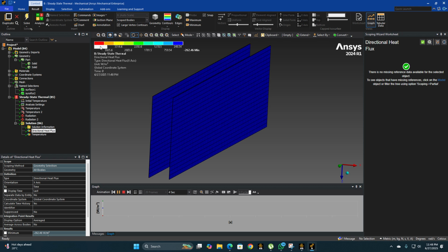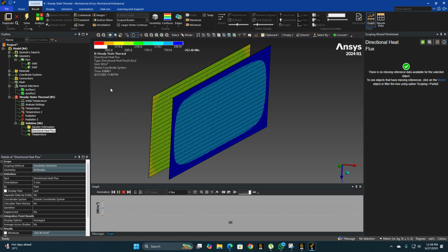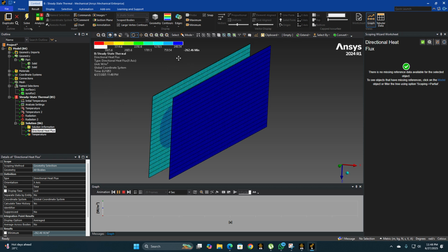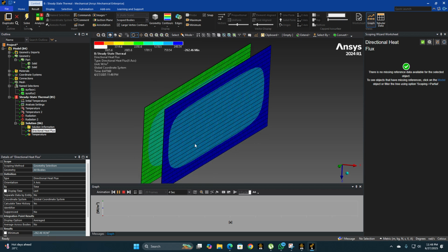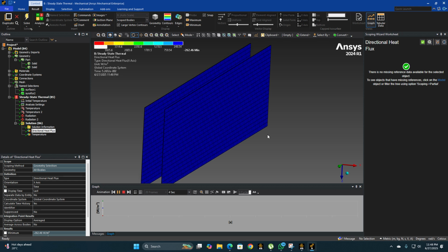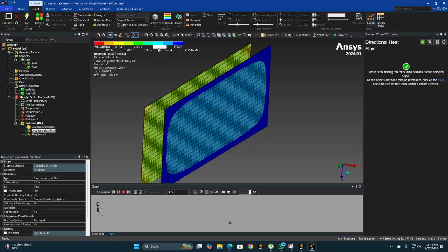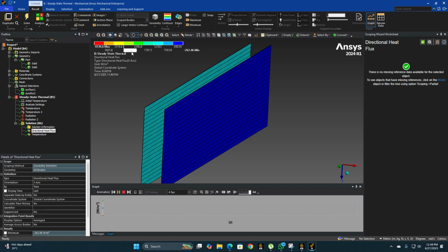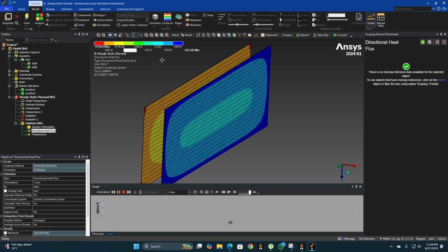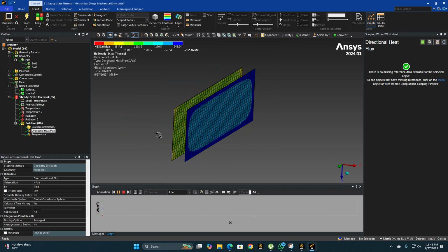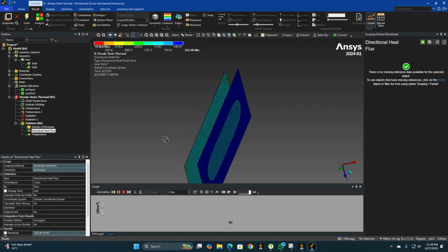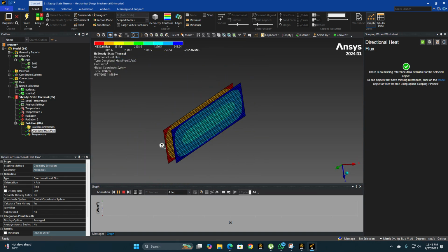You can see a much higher heat flux here, 4336, and much lower as well. And you can see much of the surface is getting the heat and going in this cyan color region, which is of 1270.5 watt per meter square. So now save this and just give it a proper orientation that it looks fine. Let's zoom it properly.